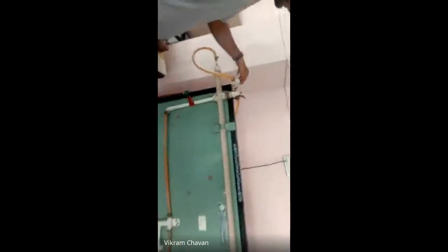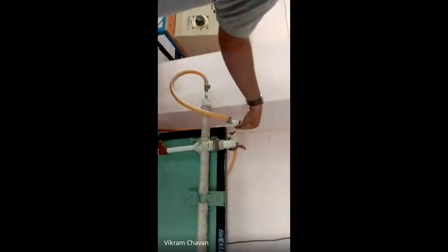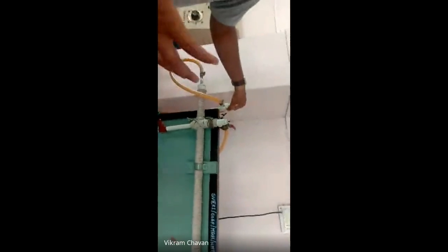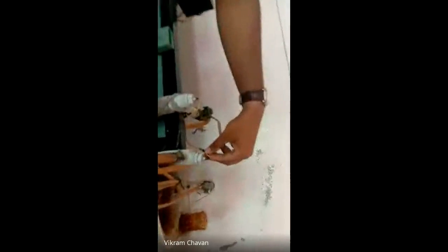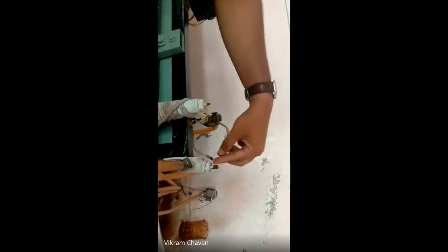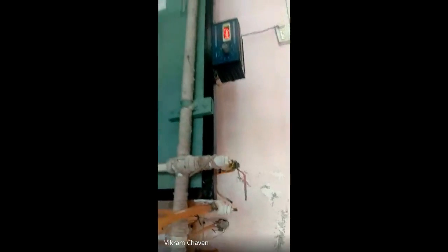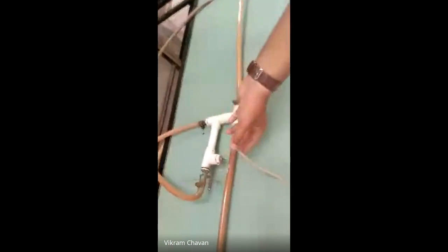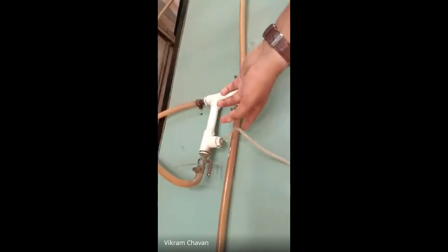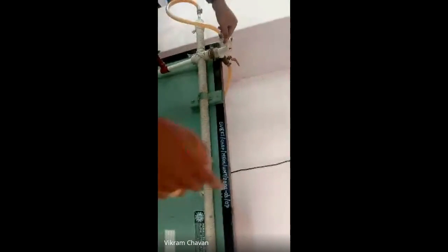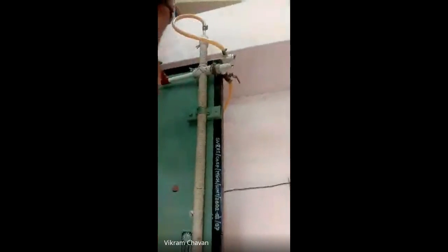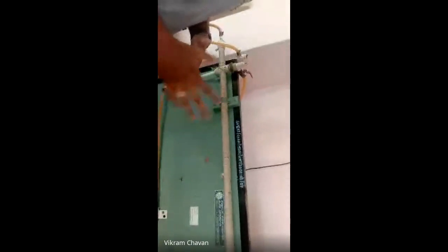we have to take first of all the T1 temperature, and that will be measured over here. That will be the inlet temperature of the hot fluid, and then the T2 temperature, once again on this side. We have to take it on the opposite side, and that will be measured over here. Third is at this initial location, the cold fluid inlet temperature. We have to take that reading over here, and the last one is the T5 temperature, which we have to measure over here. So T4 in this case we have to skip. That is the exit temperature of the cold fluid for the parallel flow arrangement.